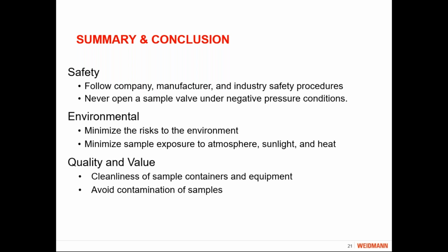Environmentally, you want to be responsible with the oil that you're pulling out. Don't just dump it on the ground and bury it. That's why you use a catch basin, put it into some kind of container, and then depending on the type of oil you have and whether or not it's PCB contaminated, dispose of it properly. Again, after you take your samples, make sure your sample containers are covered up and shielded from direct sunlight, and keep them as cool as you can. Don't leave them sitting out in the hot day sun while you're doing your duties. Put them someplace where they're shaded or protected from direct sunlight.